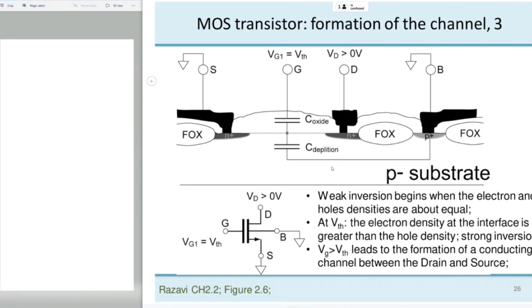Now, if the gate voltage reaches this level, which is the threshold voltage characterized in the technology, then we start collecting, so electrons from the source area can now come here. So we invert the interface in the substrate. It used to be P type, so with majority holes. We chased away the holes through positive voltage at the gate, and now the voltage is so much positive at the interface here, semiconductor oxide, that we start collecting electrons from the source.